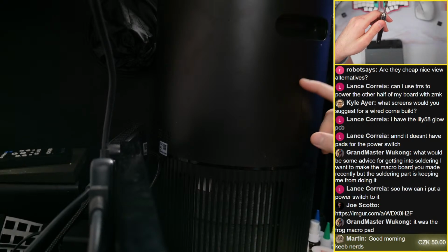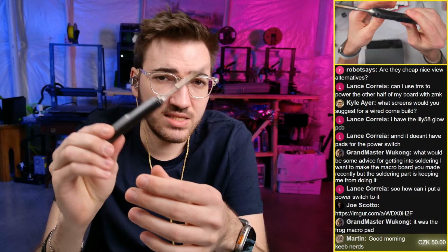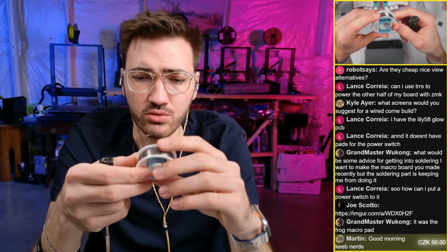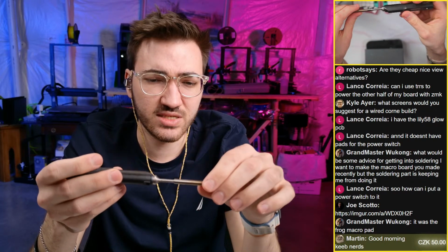You don't need this, but this is a HEPA filter, because the lead in the solder doesn't vaporize at the temperatures that we're dealing with. You do get it on your hands, which is bad. But the flux within it, most solder is what's known as rosin core solder, which is a flux that helps prevent oxidation and bind stuff better. That stuff's very bad for you. You don't want to breathe that. So keep in mind that you want to be ventilating pretty well so you don't breathe those flux fumes in and get sick, because it makes you feel sick.